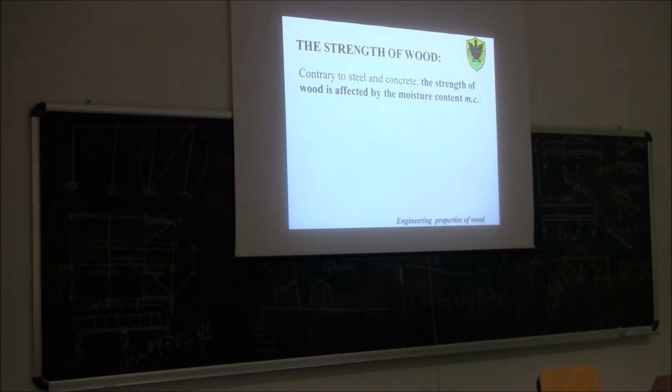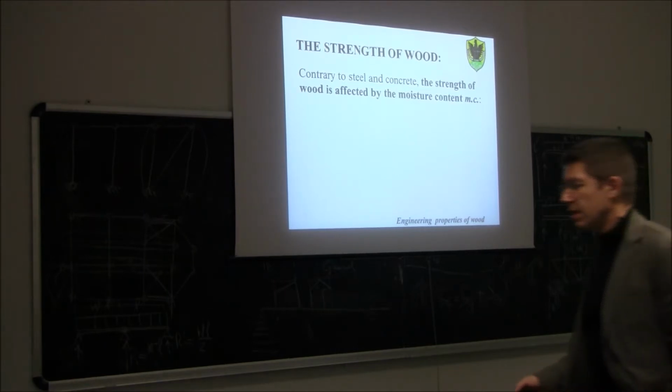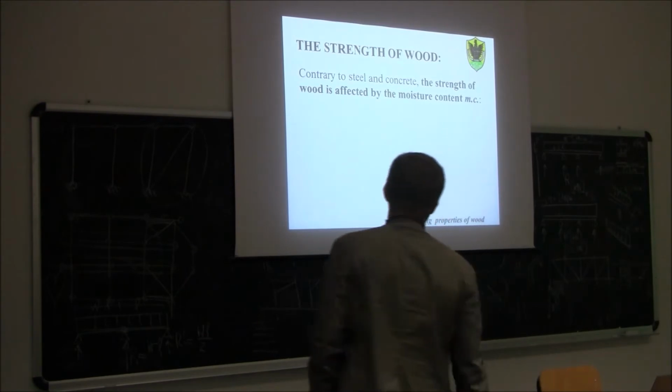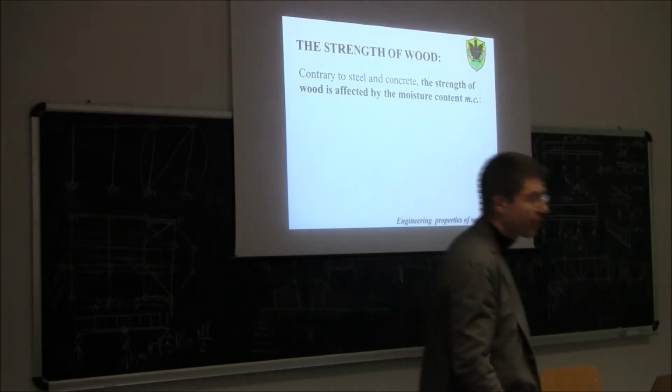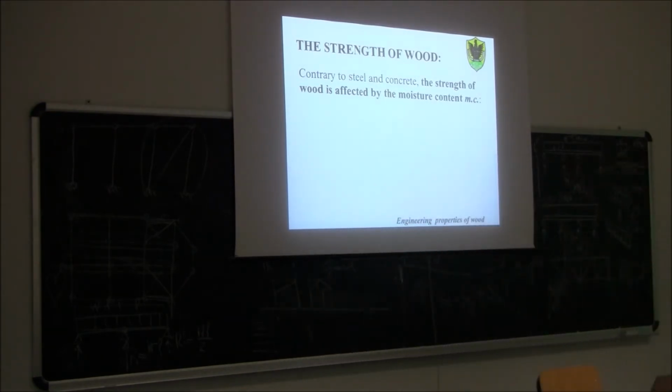So you can see that this quantity that we're going to define today, which is called moisture content, is very important because it affects the strength of wood. The strength of wood is dependent on the moisture content. In general, the greater the moisture content, the lower the strength.